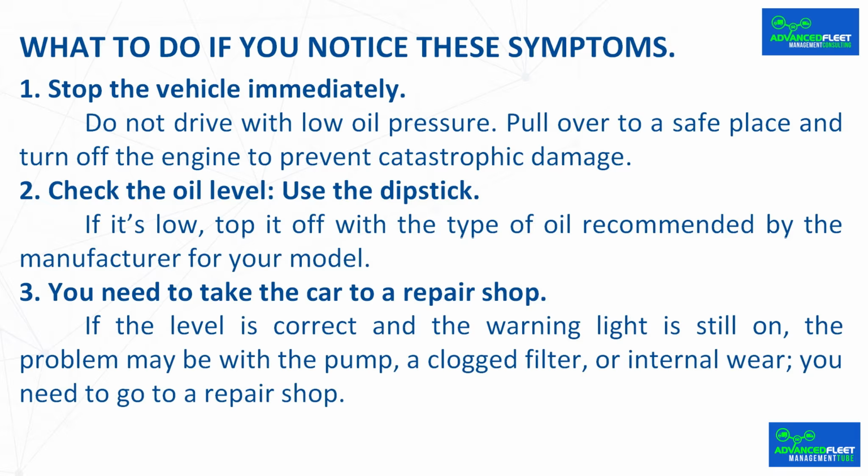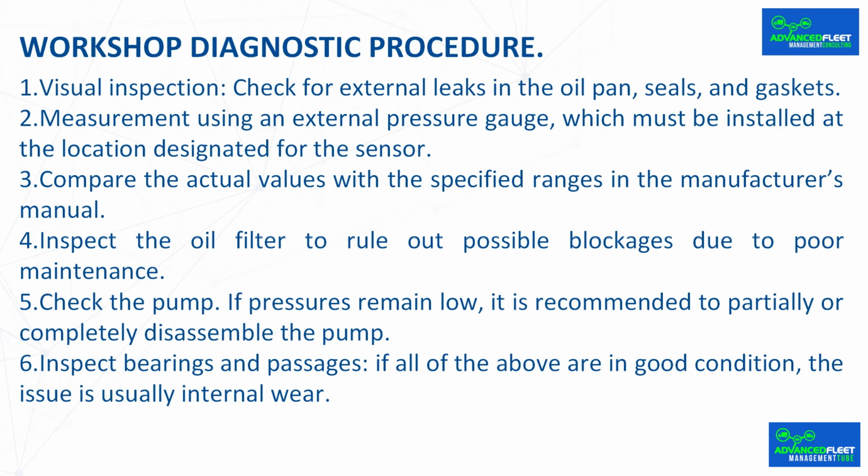If the level is correct and the warning light is still on, the problem may be with the pump, a clogged filter, or internal wear. You need to go to a repair shop. Workshop diagnostic procedure. Visual inspection. Check for external leaks in the oil pan, seals and gaskets.